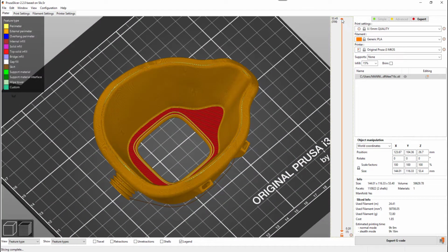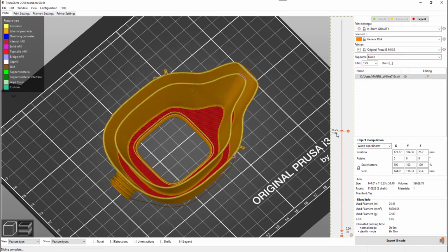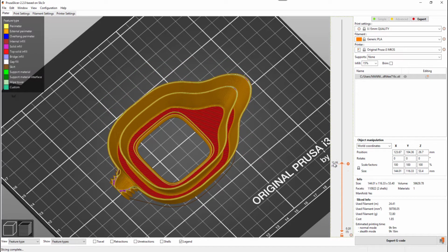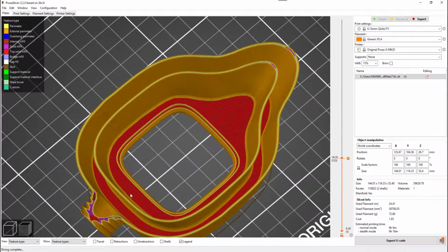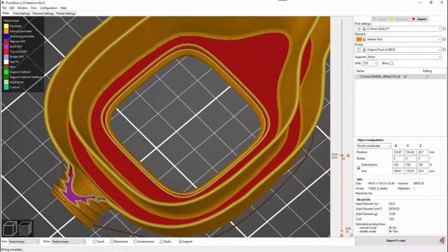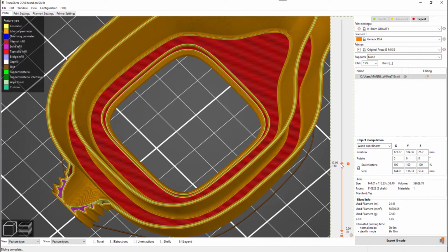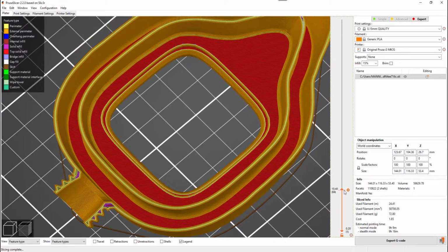You notice the interesting thing here, there are very few overhangs. You can see the hollow space in the middle, and as we get down to the start, you notice because we're using the thinner print layer, we're not getting these overhang layers because we're able to do the bridging for most of these. Now these are going to probably artifact a little bit weird. You can see here on the nozzle because there's no support, but putting supports on the nozzle would be a good way to deal with that.